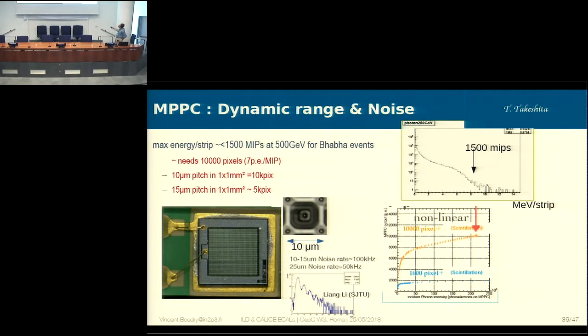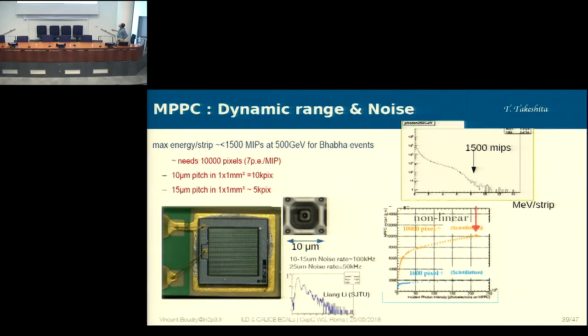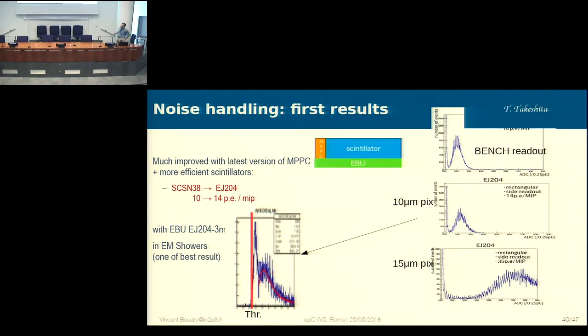This is the linearity, but you still see you have some sensitivity here, even at very high light fluxes. So the other key element there is the size of the pixel on those silicon chips and the noise, which you get spontaneously, the dark noise. This dark noise was really high, but during the last few years, it has decreased dramatically. So that was really a very nice thing. Still, they are fighting with that.